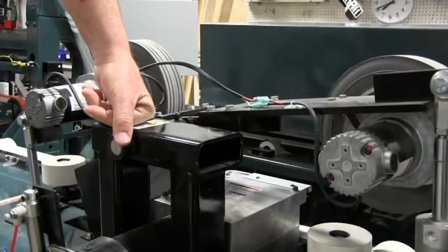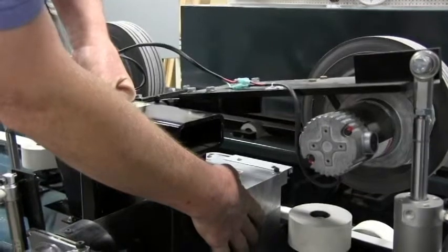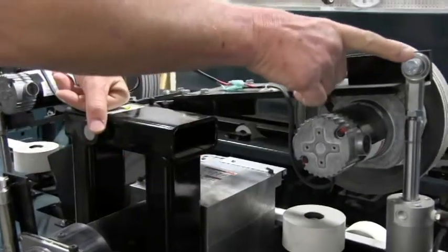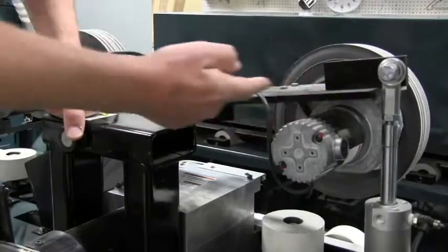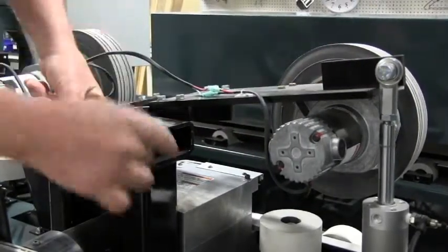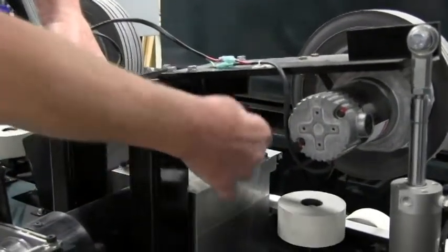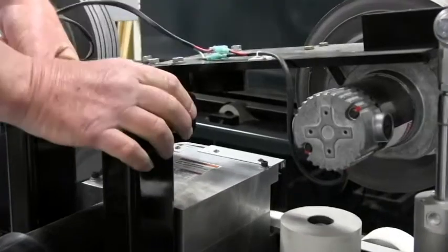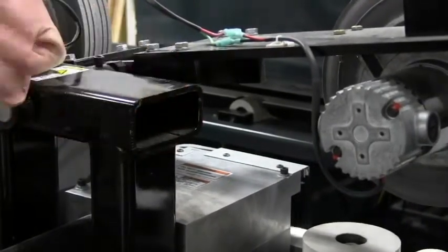When you're ready to change the Sizer blades, they are inside this aluminum housing here. To access that, we're going to take this one bolt out of the power feed drive, and then this plate and motor assembly will pivot over to the other side out of the way. There are 4 bolts in the top of the aluminum housing, and the cap comes off. You'll find the cutter head inside there with one nut on the cutter head blade.